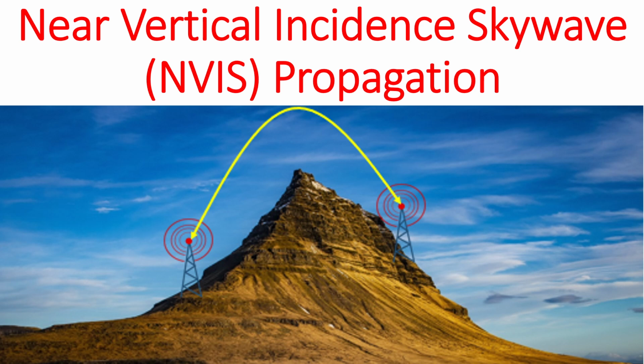In the case of usual skywave propagation, the antenna directs signals at a low angle so that they are reflected off the F layer of the ionosphere to a larger distance, favoring DX operations. Both vertical antennas and inverted V antennas have a low angle of radiation.